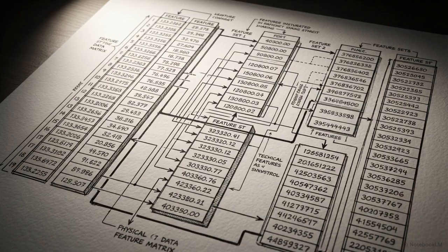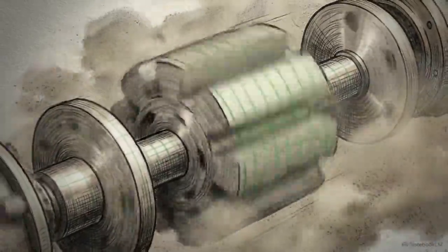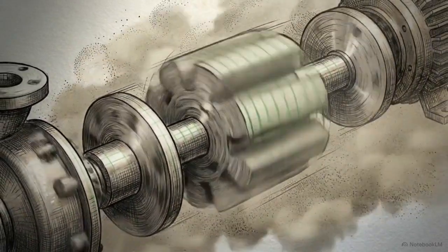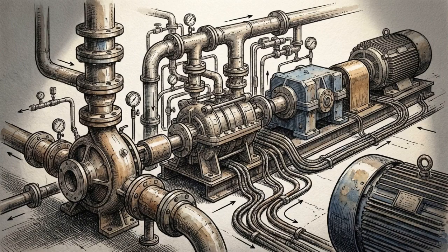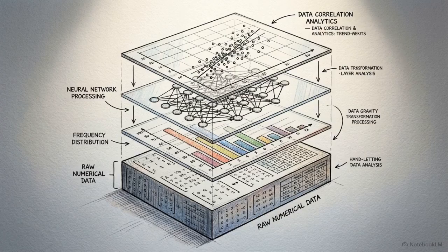The machine learning models require clean, physically meaningful features. We use deterministic mathematics to isolate mechanical reality first, actively preventing the algorithms from reacting to raw noise. No single statistical model can detect the entire range of mechanical and electrical failure modes within an industrial pump train. We deploy a robust 7-strategy ML.NET ensemble. Algorithms like operating cluster segmentation and neural networks process the exact same feature window in parallel, creating a cross-verified health assessment.